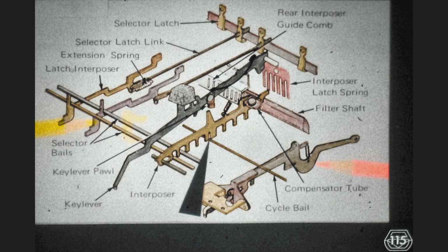As mentioned, the second adjustment is the angular position of the character interrupter. It is changed by loosening the set screw which holds the character interrupter lug to the support shaft. When the cycle clutch latch link has been allowed to move toward the front of the machine, the vertical clearance between the character interrupter lug and the lower edge of the cycle clutch latch link, at the point indicated by the red pencil, should be minimum.